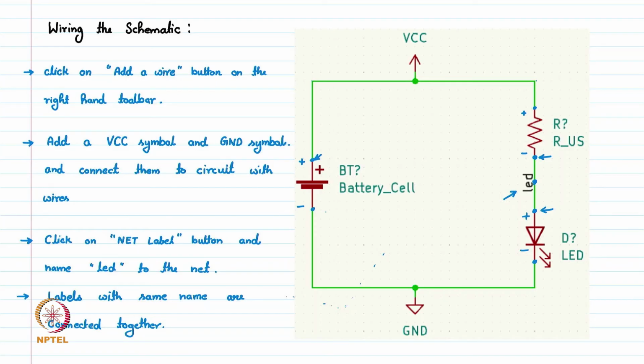This is used for making the schematic more readable, so that we do not have so many wires going along from left to right. We just simply name them the same, and we do not need to lay down a wire in the schematic to have them connected.